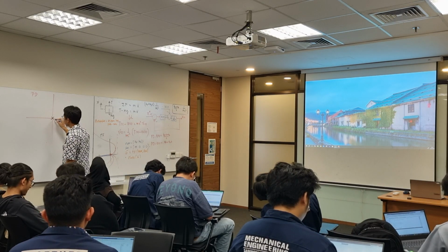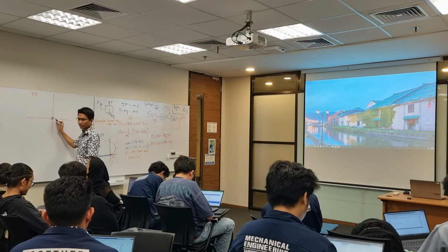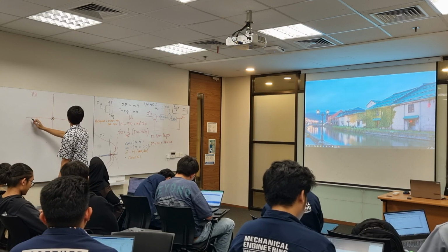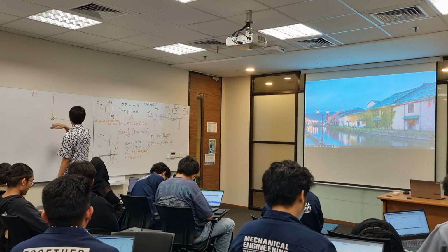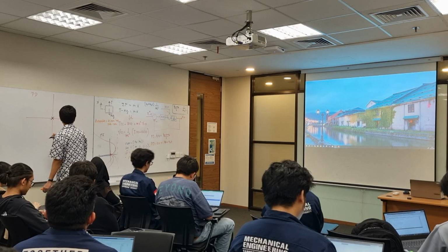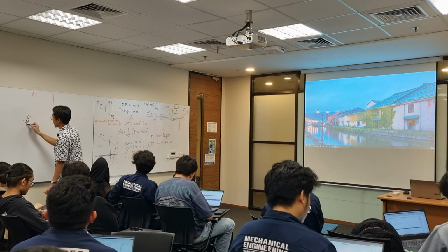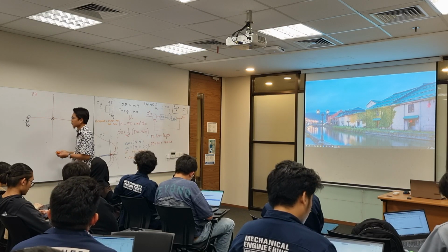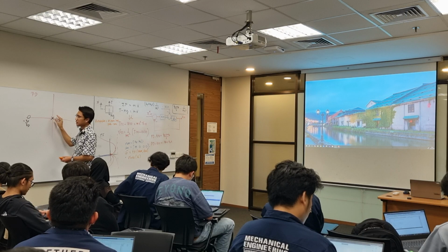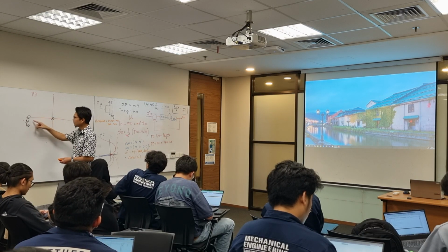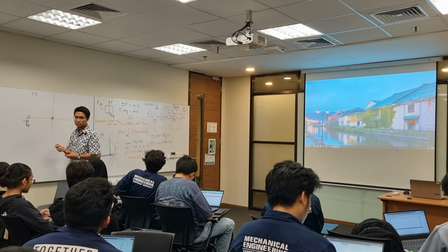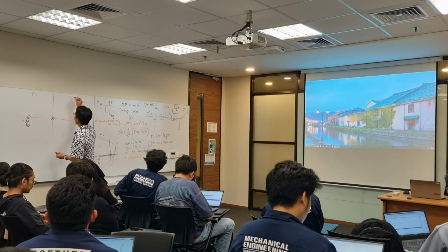Two open loop poles in here, 0, and then 1 open loop zero at minus KP over KD. So there are 2 of them, and then 1 zero, right? So we have 1 asymptote.